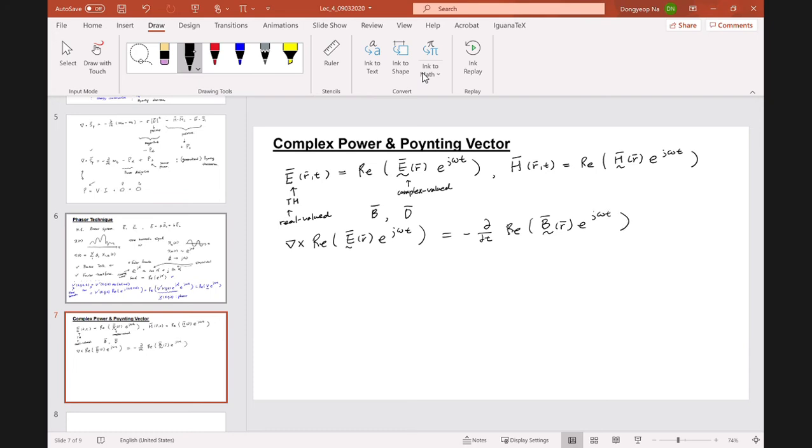Okay. And then we can write the term on the right hand side more simply, because this rotating wave is only a function depending on time. So the action of the time derivative results in just each phasor times j omega and the rotating wave term.